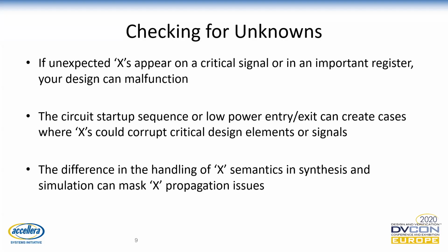So if a critical signal or register becomes unknown, your design may malfunction. Additionally, there may be cases where design initialization or even low power mode entry or exit could corrupt design logic. Designers must also be aware that the differences in handling X semantics in synthesis and simulation can hide X issues and their effect on design logic. So designers should not rely on simulation alone to find these issues.